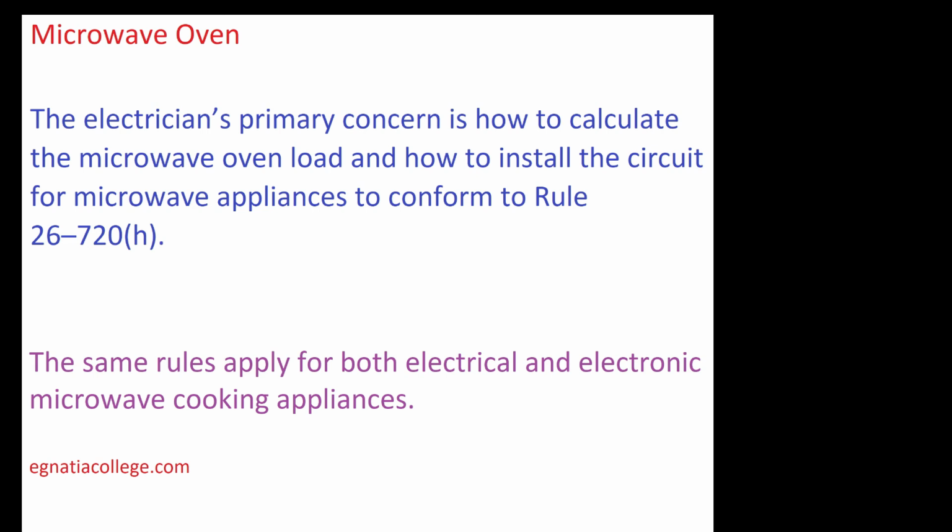Microwave oven. The electrician's primary concern is how to calculate the microwave oven load and how to install the circuit for microwave appliances to conform to Rule 26-720H. The same rules apply for both electrical and electronic microwave cooking appliances.